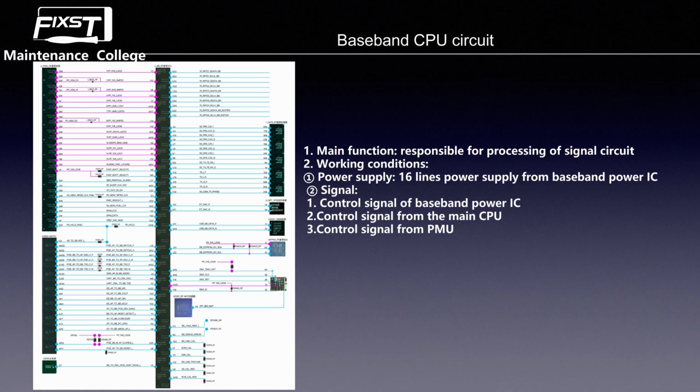And we see the U14 and W14. These two lines is the baseband CPU to the USB control IC, the data signal. And go down, you see that the J23 and J102, these two lines is connect to the baseband EEPROM. And the baseband EEPROM have a lot of the baseband verified information. If the baseband EEPROM have some problem, the phone will not have baseband and cannot repair.